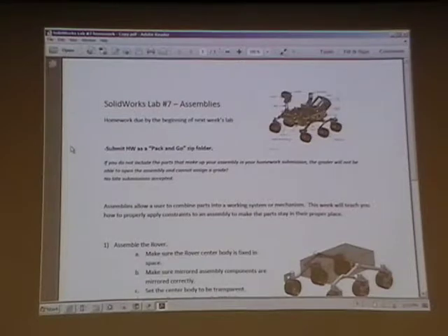Now, the Sketch Picture tool allows you to take a photograph or any other image file and actually import that image into a SolidWorks sketch so that you could just trace over it. For example, if you were going to create a SolidWorks model of something like this mouse, some oddly shaped object, it would probably be easiest to just take photographs of this mouse from above, from the sides, from the front and the back, bring those photographs in on different sketch planes, and then just sketch some splines over the edges in the picture